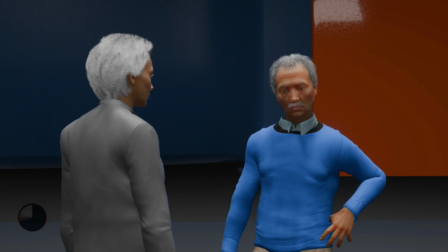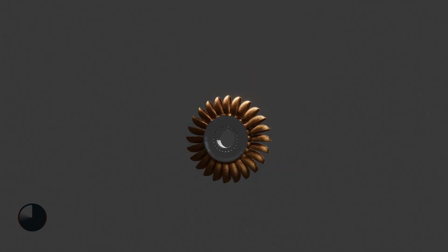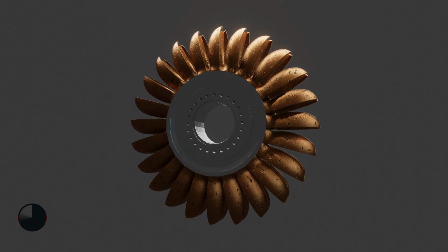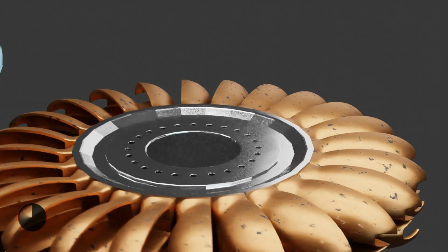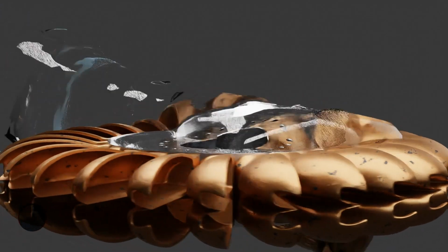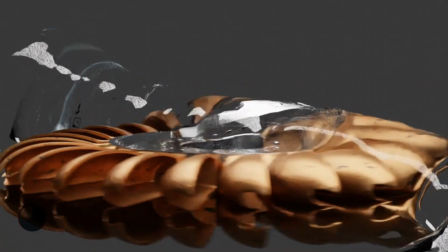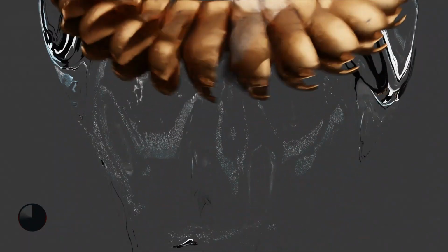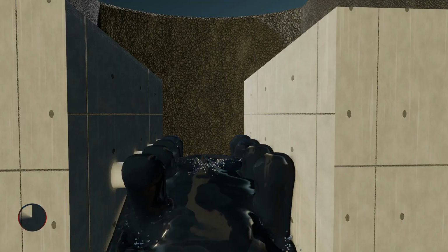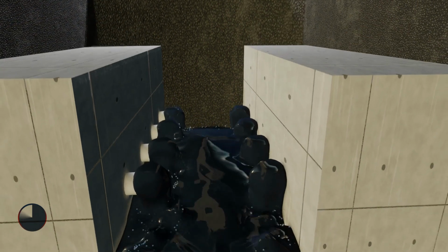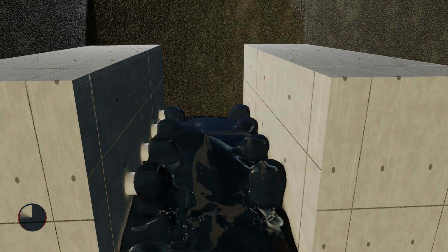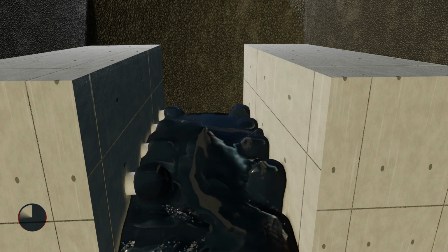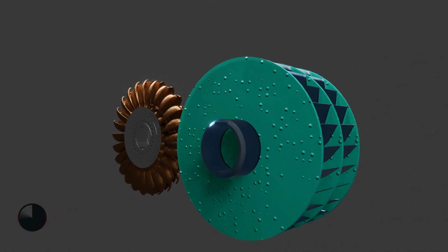flow rates. Impulse turbines, on the other hand, generally use the velocity of the water to move the runner and discharge at atmospheric pressure. During operation, the water stream hits each bucket on the runner. With no suction on the downside of the turbine, the water flows out the bottom of the turbine housing after hitting the runner. An impulse turbine is generally suitable for high head, low flow applications. The two main types of impulse turbines are Pelton and cross-flow turbines.